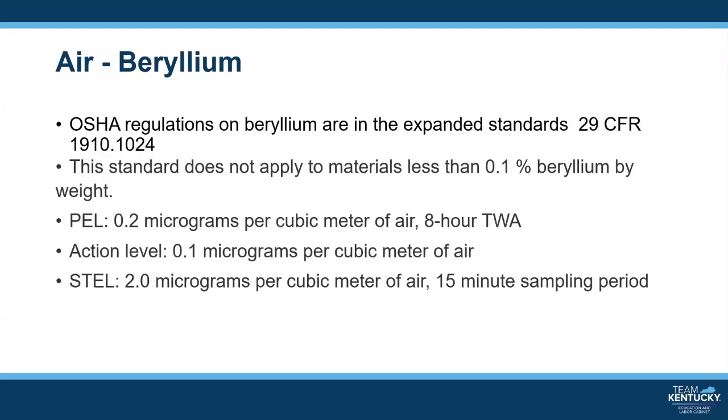The OSHA regulations on beryllium are in the expanded standards under 29 CFR 1910.1024. This standard does not apply to materials that contain less than 0.1% beryllium by weight.